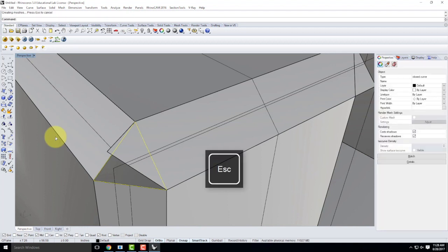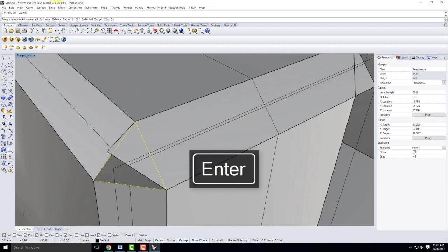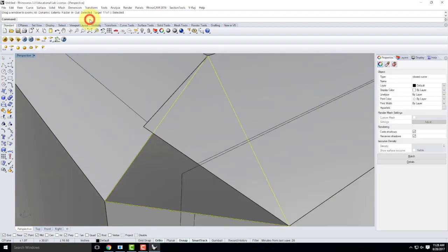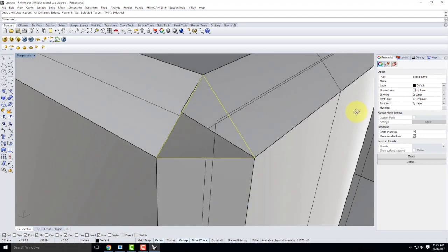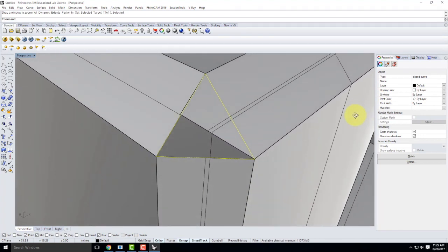I can come back to the trim. I'm going to use zoom, which we're used to, but I'm going to zoom selected. Notice I have that triangle selected. When I choose S for selected, it recenters my view around that one object. So now all my orbiting goes around that object. That object stays in the center, and everything else, no matter how big it is, doesn't matter. So this can save your life quite a bit when you're working on small scale stuff versus a really big drawing.